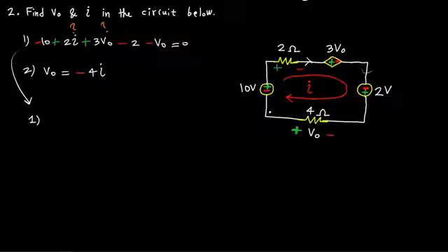So that equation is going to be negative 10 minus 2, that's going to give us a negative 12. Let me just go ahead and quickly get to the bottom of that. Then there is a 3V0 minus V0, that's a 2V0. Now, apologies if this is taking too long. I'm just trying to make sure that everybody understands every single step here. Otherwise, this would have been solved way quicker. So minus 12 plus 2V0 plus 2I is equal to 0.